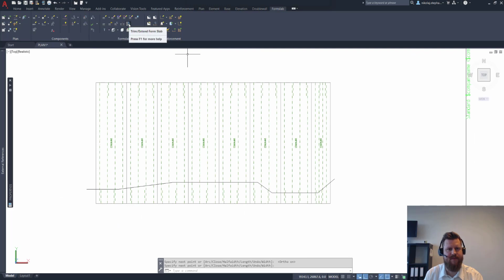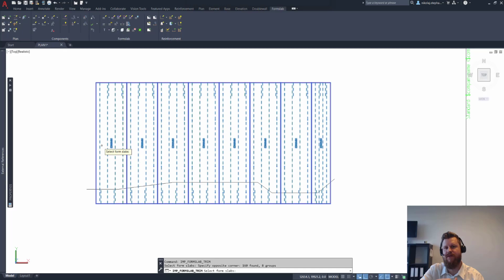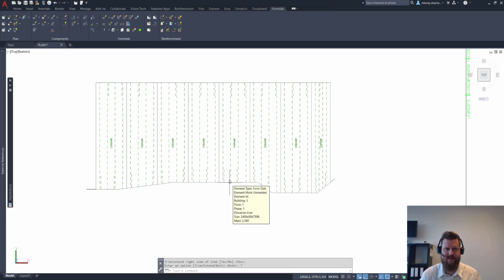So I'm going to make it cut like this. So let's say this is the wall or the facade of the building, or you have a 3D model that you have below or an XREF and so on. Let's trim and extend to this one here. Yes, please take the right side and trim it. There we go. So now we have our shape.